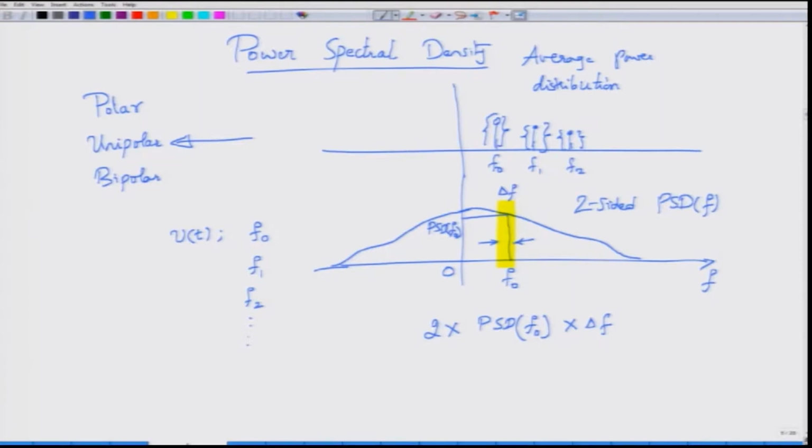In fact, when we talked about noise, we wrote some spectral density formulas. We said the noise associated with a load resistor RL has a power spectral density of 4kT by RL. If you then consider a particular band of frequencies with a bandwidth of B centered at some f0, in this case the power spectral density is flat, it does not depend on f0.